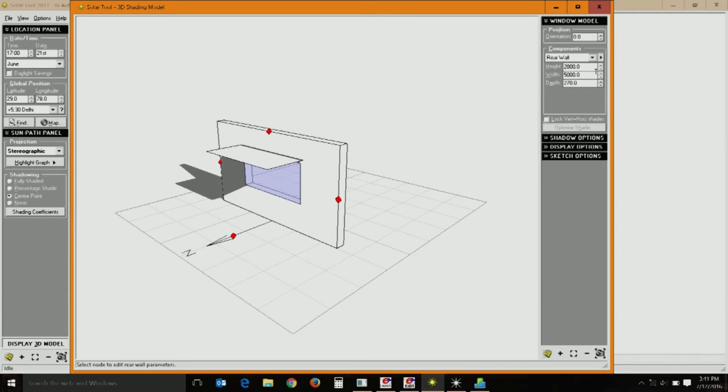If you click on the wall, you can adjust the height of the wall, you can adjust the width of the wall, and you can also adjust the depth of the wall. Depth is crucial because if you give recessed window kind of arrangements where your wall is say 500 600 mm thick, a bulk wall, where you have a recessed window, or you are giving certain cupboards and all that, the window is recessed, you do not have a shading system actually, but it is a recessed wall system. You can use this depth, you can increase the depth, then your window will be on the inside, so you can calculate the shading efficiency.